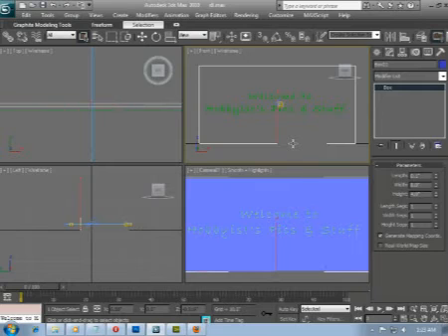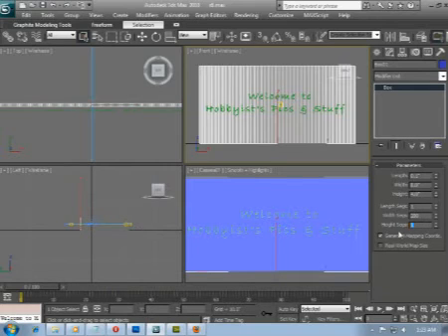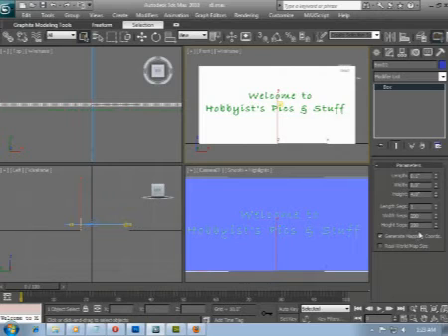The Modify tab and Parameter sections are open, so let's set width segments to 200, and height segs to, well, it actually doesn't matter as long as we use at least 200. See, if we enter 300, 3ds Max sets the value right back to a maximum of 200 anyway.